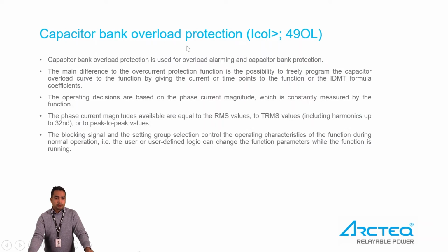So the overload protection. Overload protection is basically the same as overcurrent protection, but there is something unique about it: you can do a definite time setting and also IDMT. And the IDMT formula in the IED is the most advanced one.